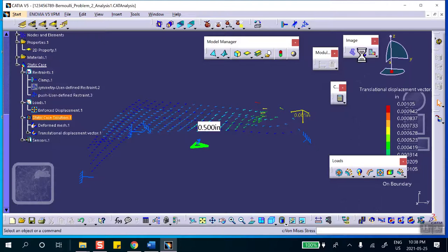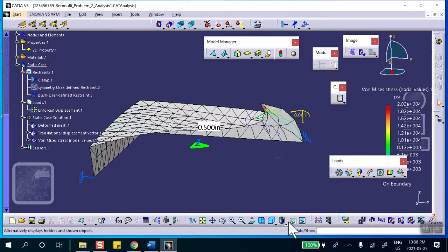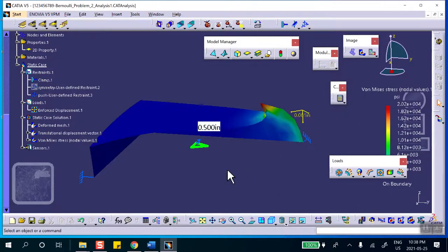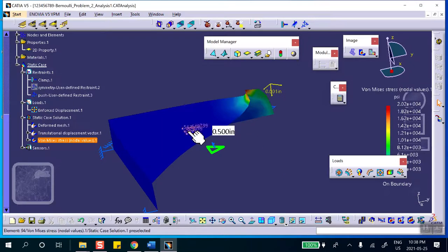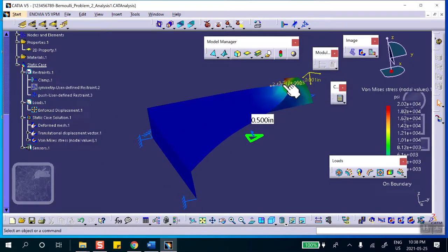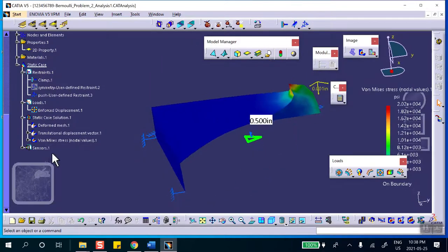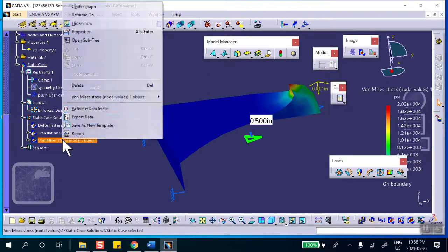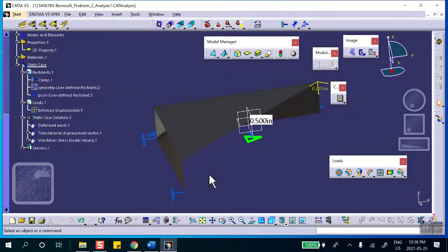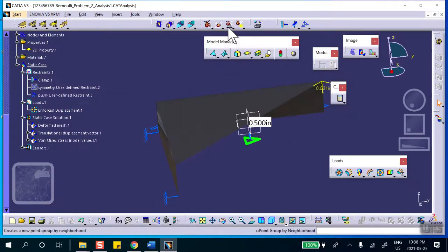So first of all, von Mises stress is right here. Let's change the rendering right there. Now we want to stay away. If you want to see the real stress, let's stay away from this, because this is a gigantic stress right underneath the needle point, right? So what we're going to do, to see the stress distribution here, which is right now overwhelmed by that guy, is deactivate this, make a box or make a sphere which is away from that box group or sphere group.